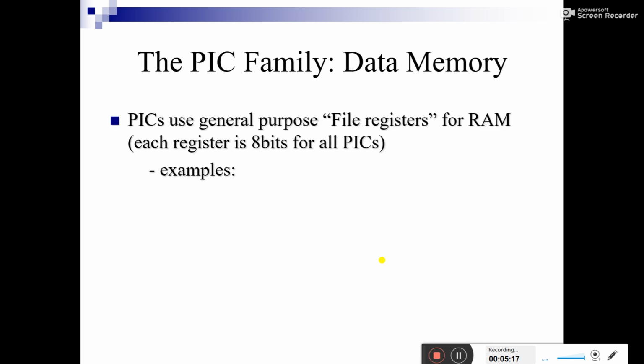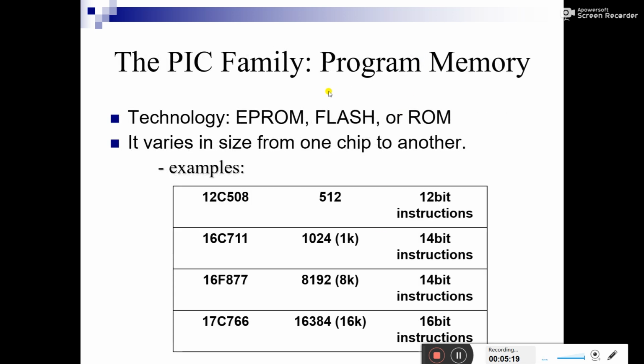Here is the program memory of the PIC microcontroller. The technology is EEPROM, flash or ROM. These types of memories are used for the PIC microcontroller, and it varies in size from one chip to another. The 12C508 has 12-bit instructions and only 512 bytes of memory available.